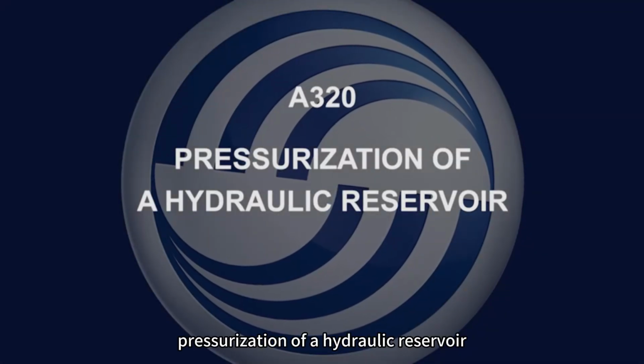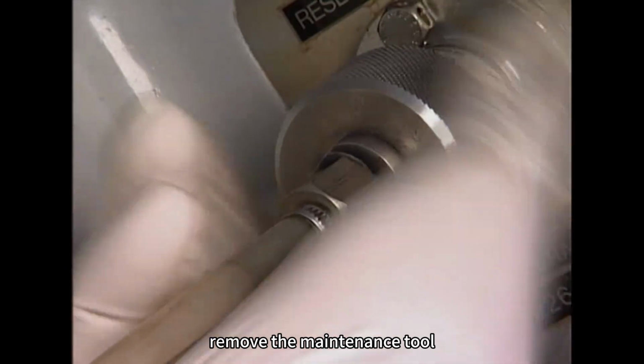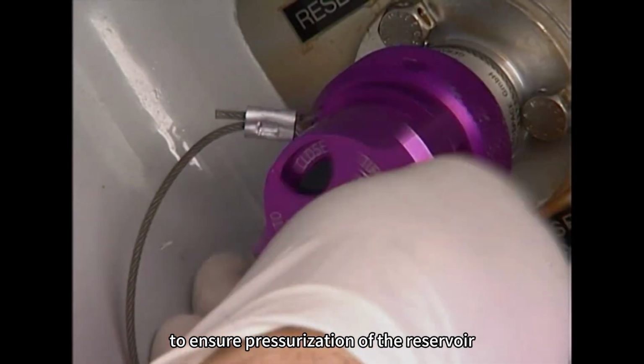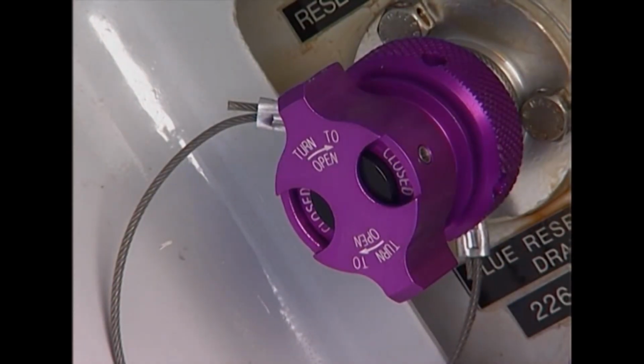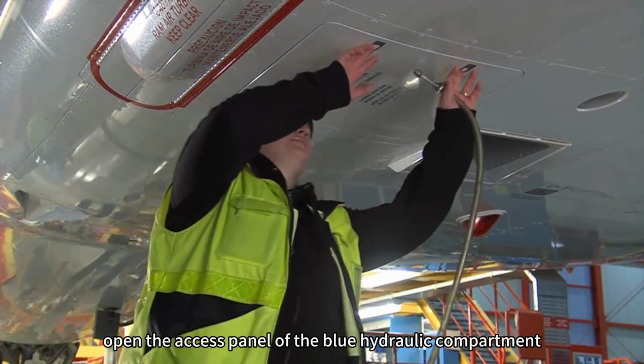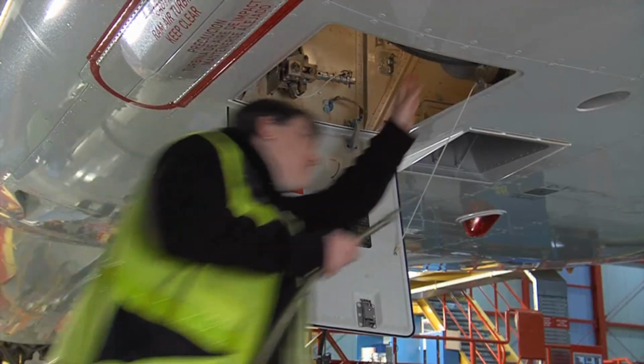Pressurization of a hydraulic reservoir. Remove the maintenance tool and install the normal depressurization valve to ensure pressurization of the reservoir. Open the access panel of the blue hydraulic compartment.